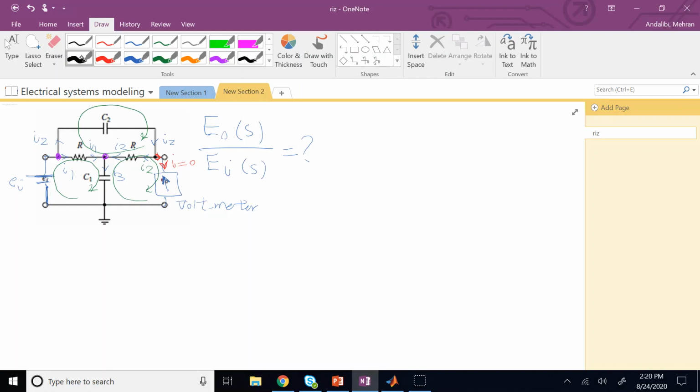So if you do that, in this node here, I have what? Some I is going in and some I's are coming out. So clearly, what is this I that is coming in? Because this is I1 and I2 going out. So what is this current? This one that is going through the voltage source. Clearly, if you call this current I3, as I said, this I through this part here is I, and that I is 0. So when I3 comes down here and 0 is added to it, what goes out? I3. So this current that goes here in is I3 goes in, and then I1 and I2 are getting out.